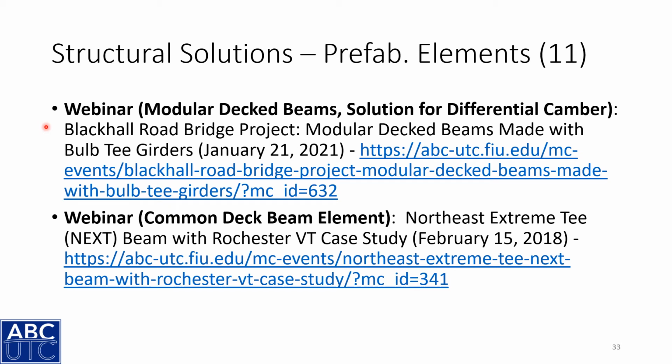And then a deck is cast on each girder in that final configuration. This allows the deck to be cast, taking into account the differential camber. The second webinar here looks at NEXT beams, which is a common deck beam element that started in the Northeast, but now it's being used around the country.